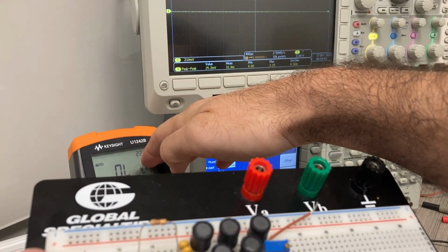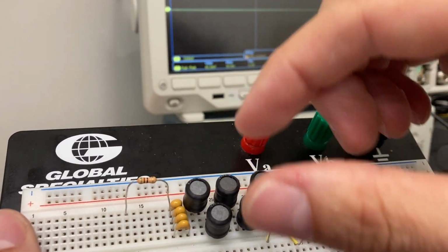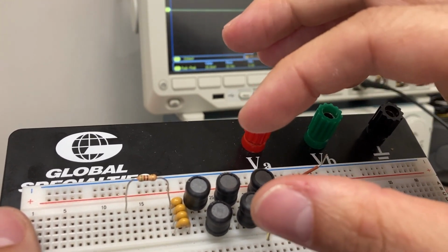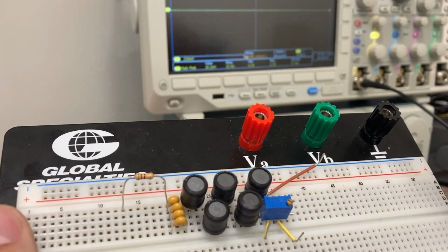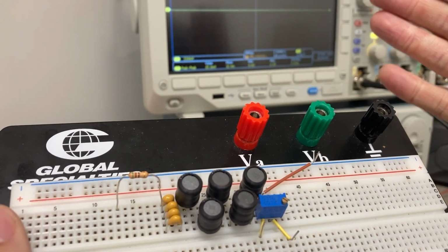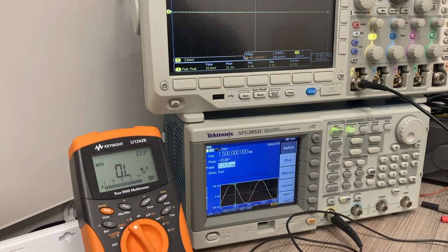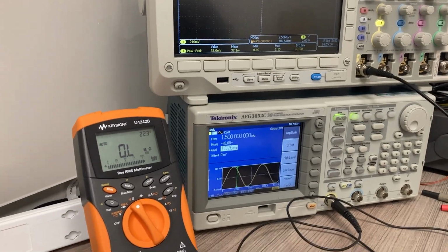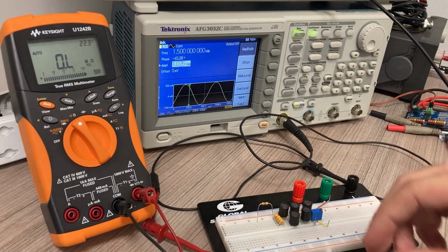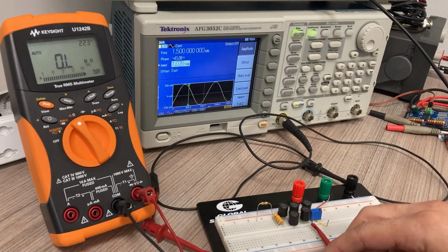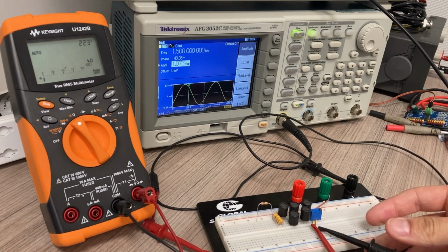I'm just going to collect my resistance values, go incrementally 1 at a time. But later you can compensate for that and say, you know, I had an additional 9.5 ohms that I can't remove from the circuit, and so then all my values are shifted, right? So anyways, hopefully that suffices as an explanation. Let's get started here. Let me make a slight change here. So first, I want to simply measure my resistance value on my potentiometer. I connect the leg here and here.